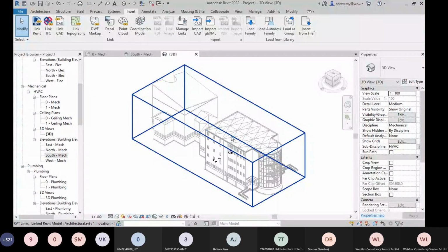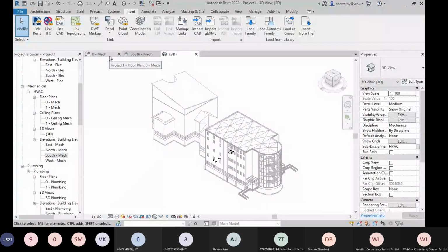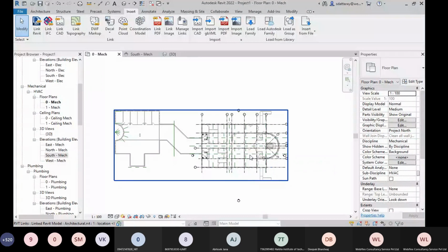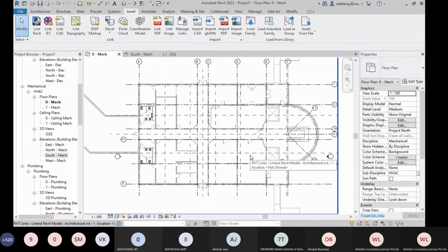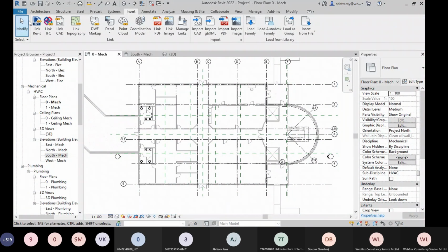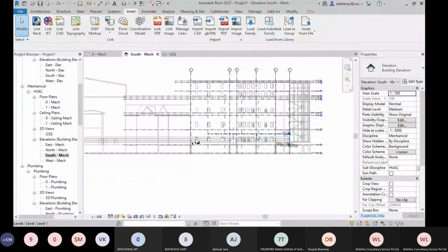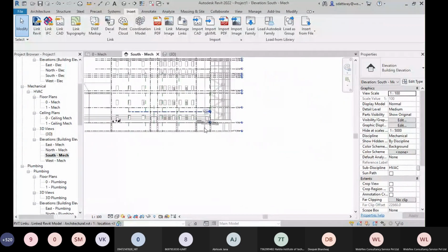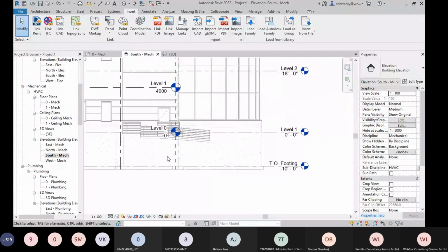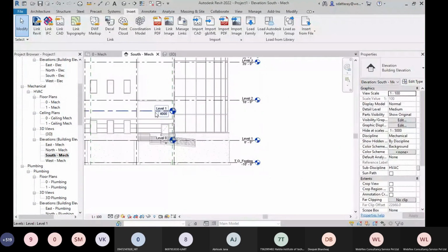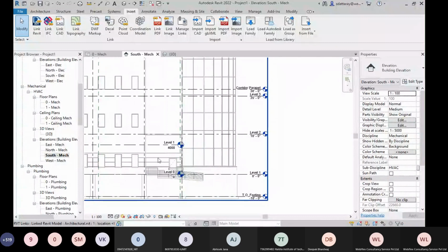So that's why I told you earlier that in Revit it is done very easily, because in a single model you can see the various different views. So a lot of the work is actually less. Before we do that, we must do something. We must link this. I have linked this file to my MEP software, but it's not done yet. We have to monitor this file. Monitor means we have to monitor each and every level to our actual MEP project.